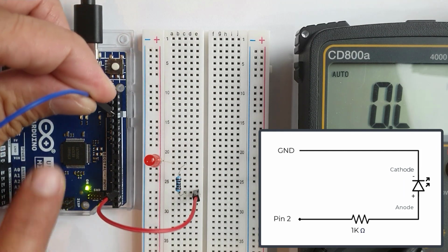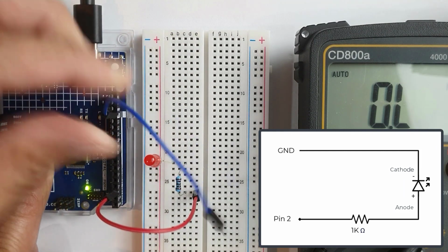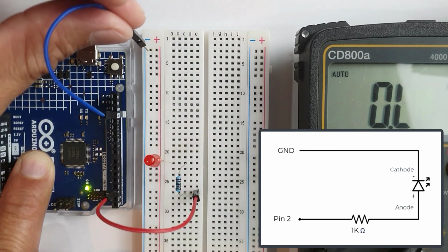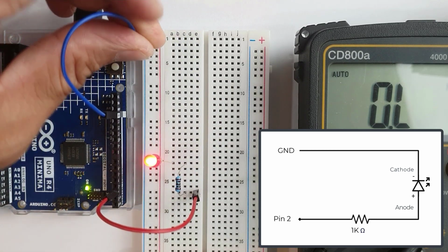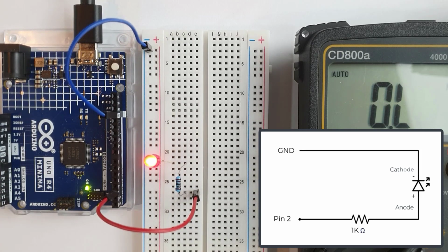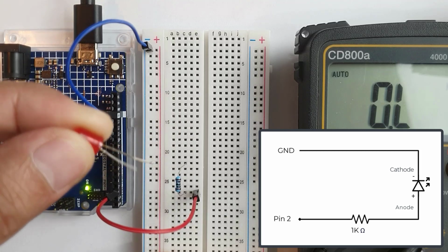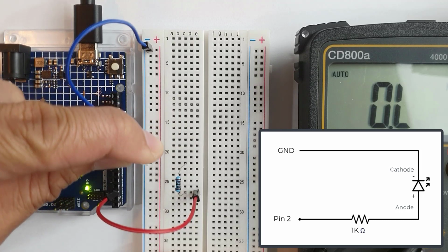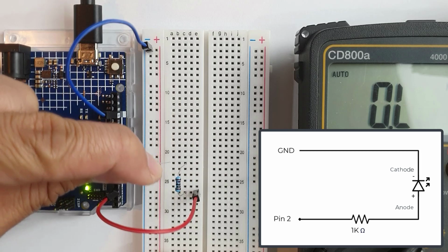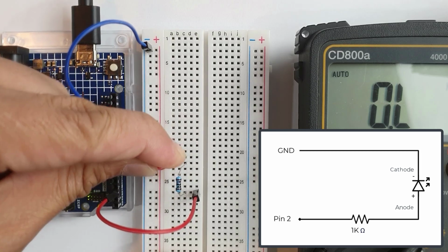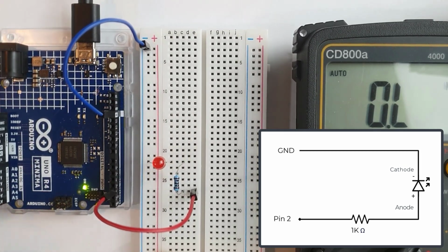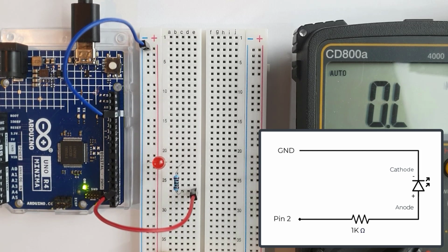An LED or light-emitting diode is a special type of diode that emits photon light when an electric current flows through it. Well, a diode is a type of semiconductor device, and the most common function of a diode is it allows current to only flow in one direction. And for a light-emitting diode, when there is no current flow, there's no light. Current flows from the anode to the cathode and never in the opposite direction.